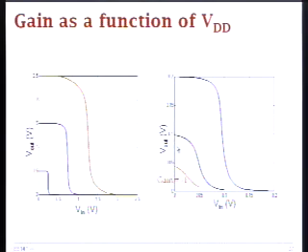It happens between maybe 50 to 100 millivolts, when thermal noise starts to matter, the kT/q noise, which depends on your temperature and is about 26 millivolts. So the good rule of thumb is that you have about 2 to 4 VT, the thermal voltage kT/q, as the limit to supply voltage scaling.